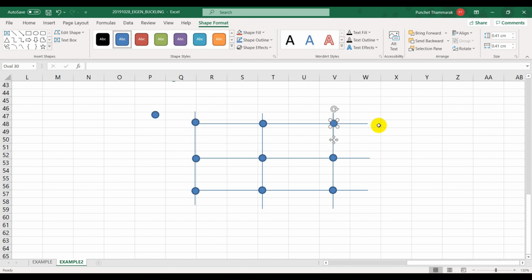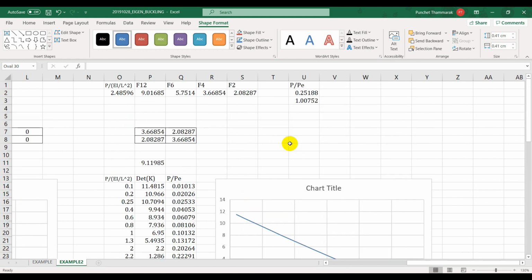But if you want to account for the second order effect, and you have seen here that you get a very bad overestimation of your structural capacity, you try to incorporate the second order effect, but the node, the degree of freedom that you have to account for second order is not at the sensitive location.